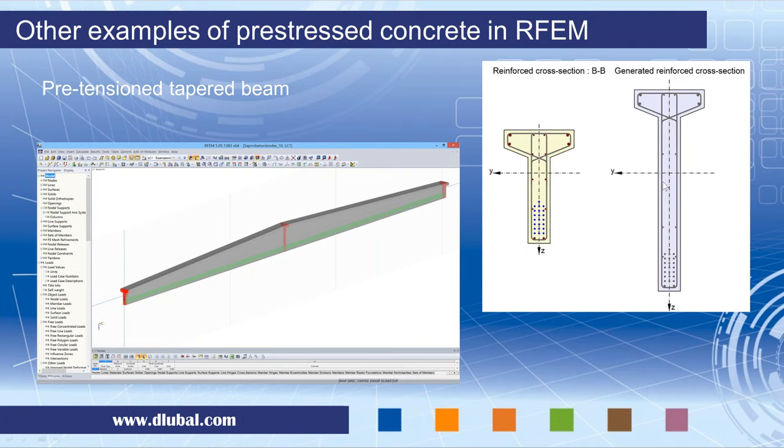In fact, if you use the templates of the reinforcement, then the reinforcement is adapted automatically along the length based on the calculated depth of the cross-section.